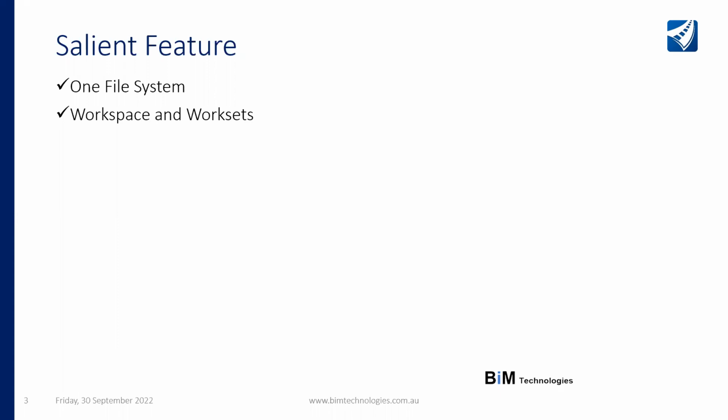And when you select a workspace and workset while creating a new project, it connects to that particular container. And every time you browse for any required resource to model your roadway, it will take you directly to that particular folder, or you could say space. So it can be on your computer, on a network drive, or on the cloud. So it saves time. Otherwise, you can waste some time looking here and there for the correct standard setting files.